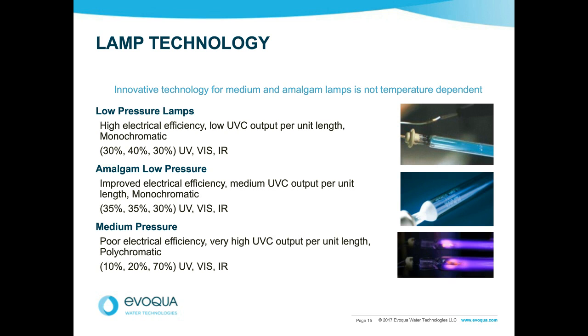The next one we have is, how does UV penetrate liquid sugar or brines to disinfect? Okay, well, we would use a different geometry reactor. For some of the brines, you can treat up to a 70 Brix brine, a high invert sugar brine, a very concentrated sugar syrup solution, which can be quite viscous. So we'd use a thin film device to disinfect some of the higher Brix sugar syrups. For brines, we'd simply use lots of lamps with small path lengths.